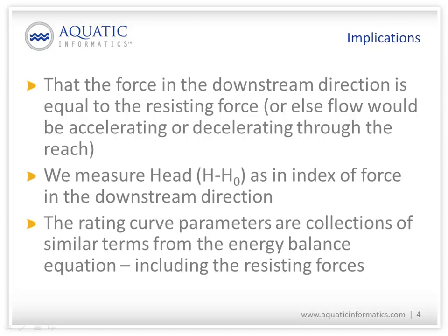There are some really important implications to these assumptions in our interpretation of rating curves. One is that the steady and uniform flow assumptions tell us that the force in the downstream direction is equal to the resisting force.